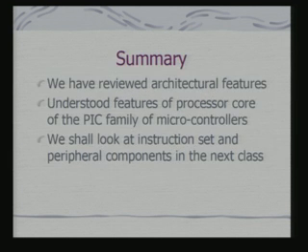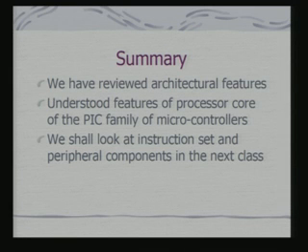So, this more or less gives me the basic introduction to the core features of the PIC processor. I am not talking about the complete PIC microcontroller, obviously, because I have not yet looked at the peripherals and the I/O ports. What I have looked at so far is the core processor, the CPU, its registers, how the program memory is organized, how the data memory is organized, and how instruction pipelining is implemented in PIC. We shall look at the instruction set and the peripheral components in the next class and subsequent lectures.